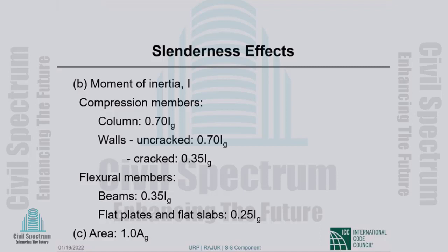I do not know that I will have occasion to discuss what I'm talking about in this lecture series. But in any case, what I'm trying to tell you is that ACI 318 basically never tells you to use these assumptions for general structural analysis. However, more and more that has kind of become practice. Okay. It is not code required. I want to absolutely emphasize that.